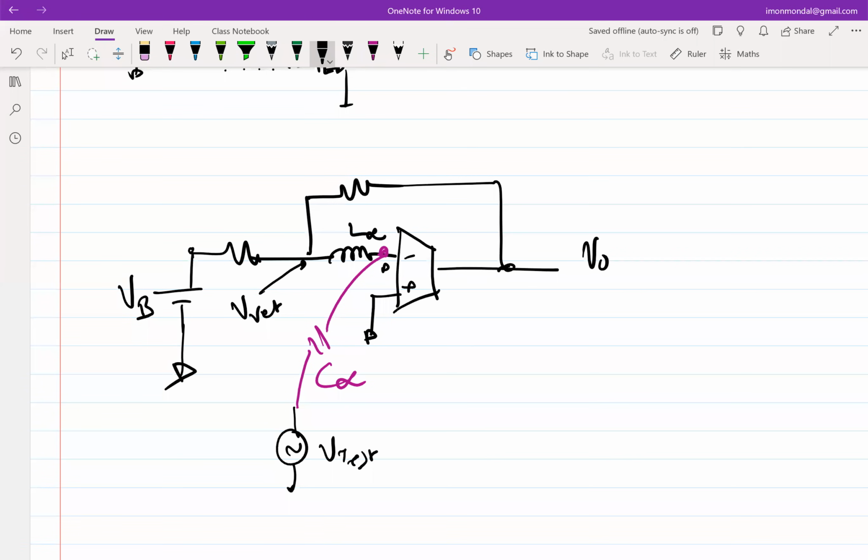I think LTspice will give you whatever value you want, right? But don't go into like terafarads and gigahenries, because then the simulator sometimes doesn't converge, because ultimately it's a numerical simulator. It wants some values in a range.